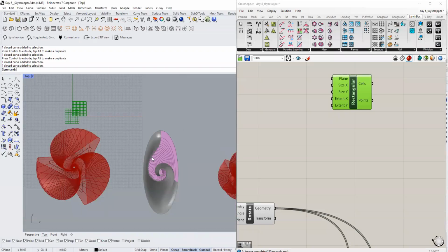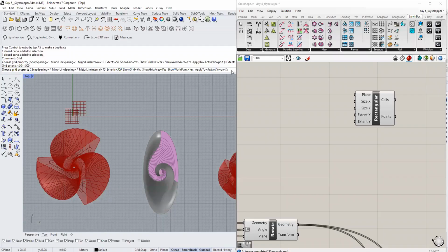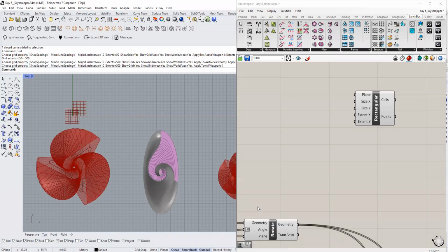And definitely the flow plates cannot be placed inside such a small cell. So I'm just going to increase it to a size. I think the length, if I increase the grid in Rhino, the grid background, you can do it by using the grid command. Let's just increase it to 500. You can see that the length is about this much, which is almost like 25, let's say 30 maximum. The width is about 20, 40, 60. So let's say 30 by 60, a grid size would make sense. I'm just measuring it by looking at the background grid.